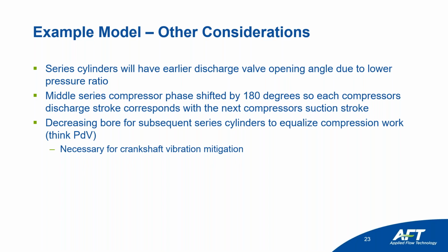And then one thing you've probably noticed about multi-stage compressor design is the bore decreases for each subsequent series cylinder. And the reason for this is so that they have the same amount of compression work. And that helps to control vibration. So if you think back to PdV in physics, that's essentially why we're making it smaller.